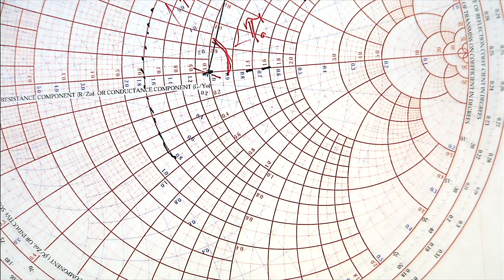So what does it mean? It means that I can simply rotate the value for Z in by 180 degrees and then look at the Smith chart and see what the value for Y is. Any value of gamma d, if I rotate it by pi, then instead of Z in, it gives you Y. Just rotate and then look at what the value is at this point. This point is the intersection of which two circles, and then that's the Y.